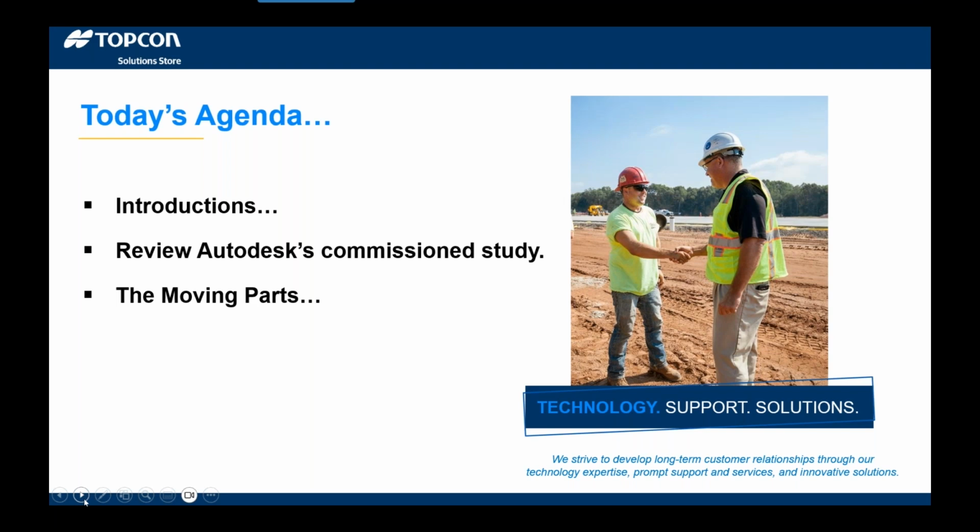But the one thing that's kind of slick about this optimization tool is it actually lets us go in and apply different zones throughout our site, and then we can give different importance through hierarchy. Once it's set up, basically we say optimize. Then it's going to try to do its best to listen to what we've said, right? It's going to go in there and say, okay, this building pad's doing this, and there are some break lines over here. There might be a sidewalk and a parking lot, even a pond, whatever it may be.